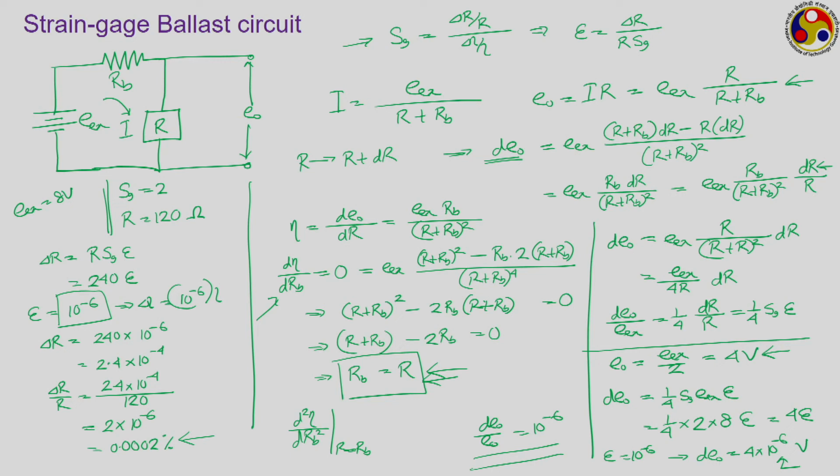While it is a very simple arrangement, quite similar to the potentiometer, using this we generally demand very high voltage resolution, and therefore it is not always the preferred option in industrial application. However, if we are looking for some kind of dynamic arrangement, this can be preferred, because there we are not looking for the absolute change in strain, but we are trying to get a profile of the change in strain. Sometimes this can give good readings, but that is beyond the scope of the present discussion.